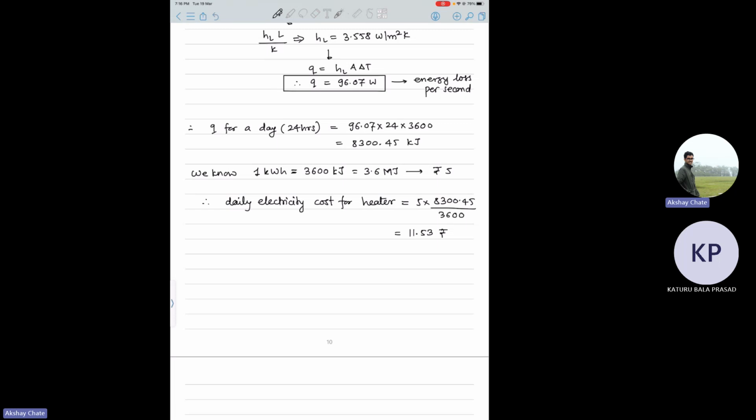So there is an important point, this boiling curve. You should study those various regimes. First is your pool boiling regime, where you have initially free convection. Then you have nucleate boiling. There also two regimes are there. Initially, there will be lesser number of bubbles, and towards the end of nucleate boiling, the number of bubbles will increase rapidly. And after a point, there will be a transition zone where alternately on the surface of your heating wire, water and vapor will be there. So that is your transition region.